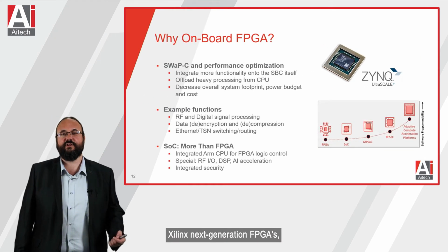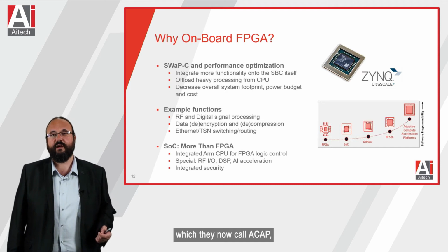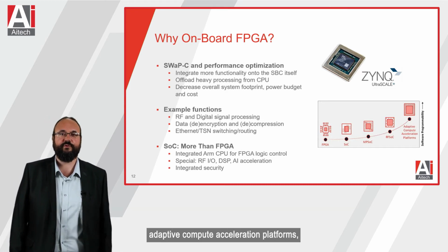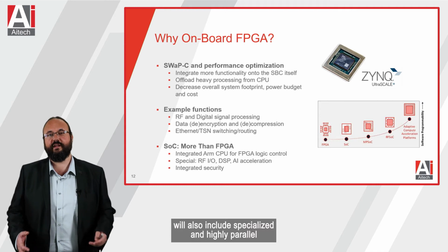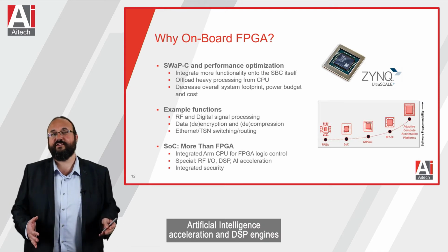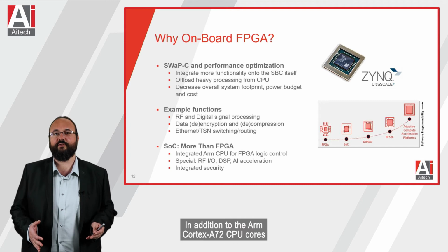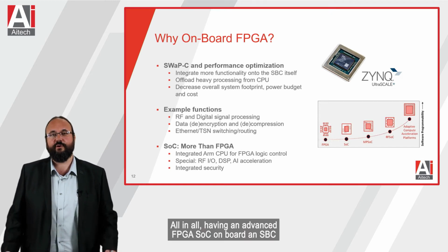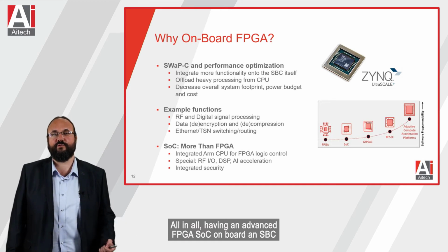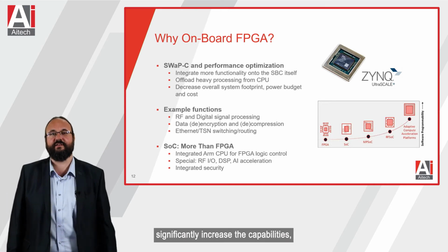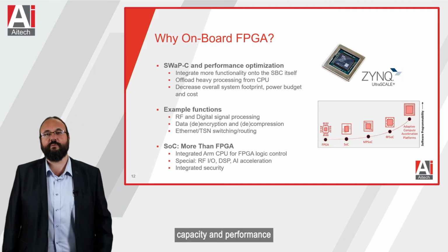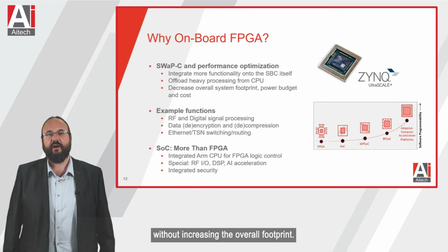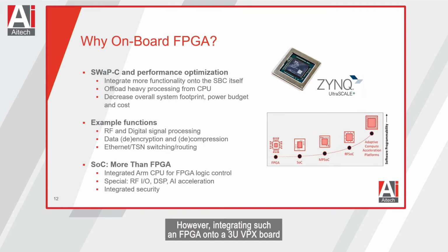Xilinx next generation FPGAs, which they now call ACAP, Adaptive Compute Acceleration Platforms, will also include specialized and highly parallel artificial intelligence acceleration and DSP engines, in addition to the ARM Cortex-A72 CPU cores and traditional programmable logic. All in all, having an advanced FPGA SoC on board an SBC significantly increases the capabilities, capacity, and performance without increasing the overall footprint. However, integrating such an FPGA onto a SWaP-C board is not an easy feat, and it greatly complicates board design and layout.